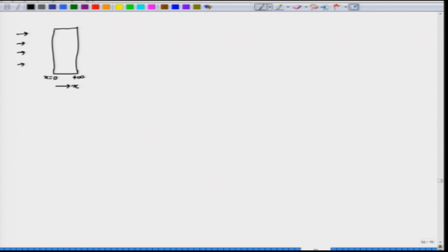The heat treatment is usually carried out and the atmosphere is maintained such that there is a constant carbon concentration at the surface. At the surface the concentration, let us denote it by C s, and typically steel will have a certain carbon concentration to start with. To make the problem simple initially, let us assume the carbon concentration in the steel before carburizing is 0, and since we are maintaining infinite boundary conditions, at the other end the carbon concentration will always remain C 0.